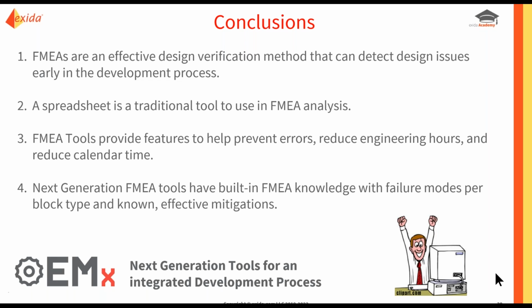The term HAZOP faded away and the term FMEA became dominant. And that's kind of where we are today. A functional FMEA is actually the same thing as a HAZOP, at least at the design level.